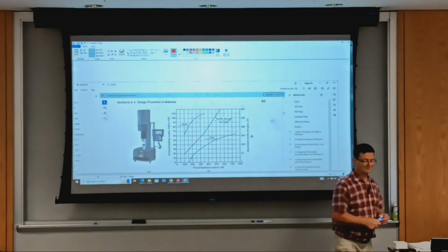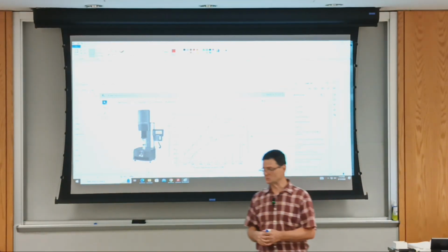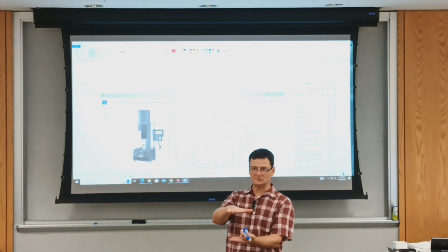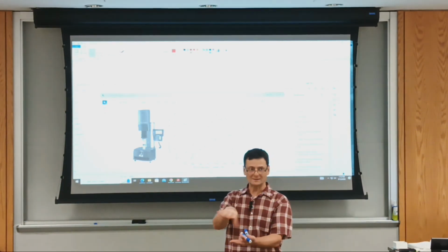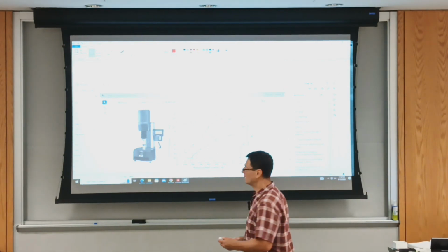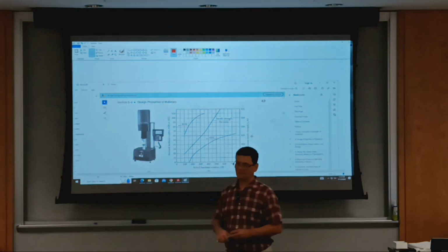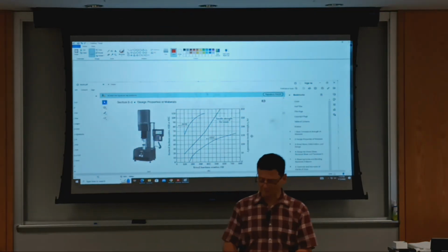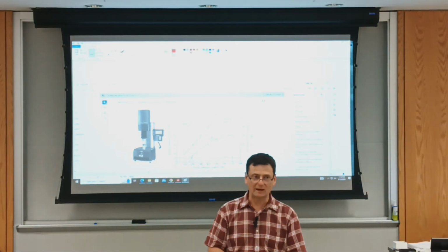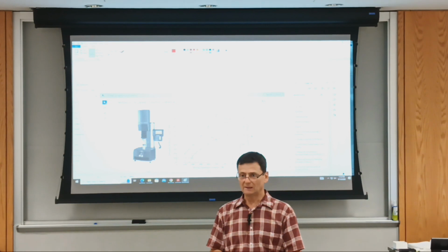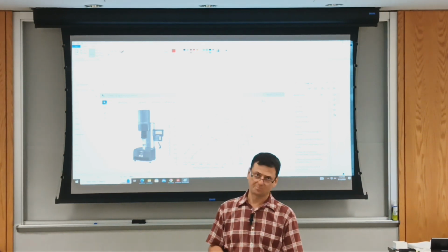So I said that hardness tests are the most convenient. All you need is two parallel surfaces with a good finish on the one that you're pressing the indenter against. Machinists do another thing. When you don't know what stuff is there, you check with a file. Can you file it? If you can, it's soft. If not, you start guessing.